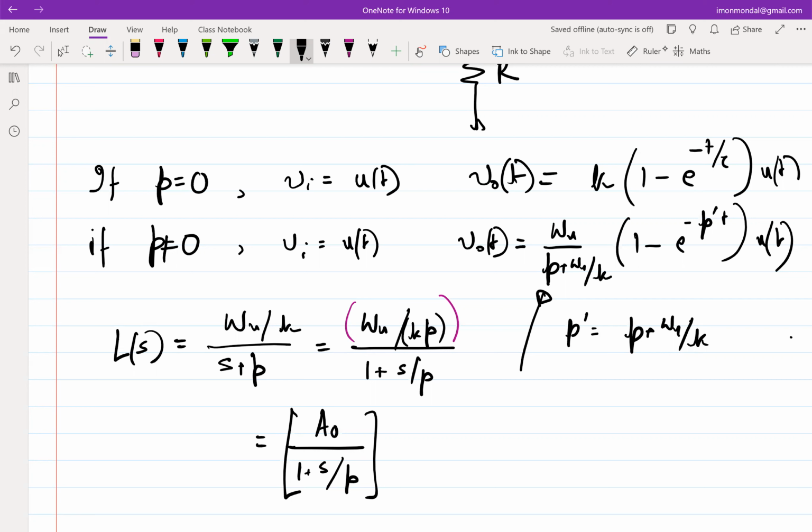Okay, so the exercise that we did here, figuring out what is the loop gain and what is the expected steady state error approximately, is also true for an ideal integrator, right? Even if you have an ideal integrator and you are operating at omega naught equal to 10p, what is the steady state error that you will get? It is the same as you will get in a real integrator case, because you are operating somewhere on this line after p. If you're operating at omega greater than p, then it really doesn't matter whether you have an ideal or real integrator, isn't it? So you are not getting anything by making an ideal integrator if you are operating beyond the location of the pole. Because after P, there is no difference between what an ideal integrator would do and what a real integrator will do.